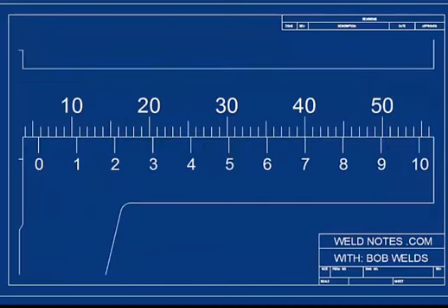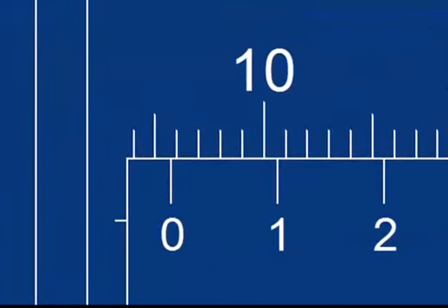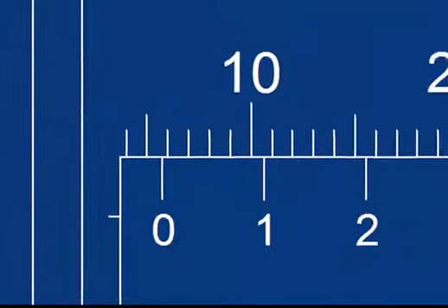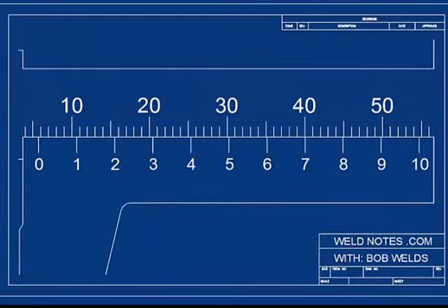I'll zoom in and let you look. Let me show you a hint about where to look on the vernier scale to see where the marks line up. You see how our pointer was a little more than halfway between marks? That means the vernier scale will line up a little past halfway. Now, do you see the mark that lines up better than the rest? It looks like the 7 is lining up. The 7 means 0.7 millimeters.